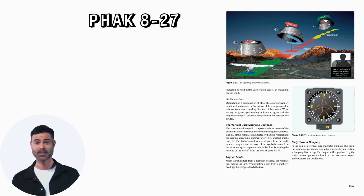Oscillation error. Oscillation is a combination of all of the errors previously mentioned and results in fluctuation of the compass card in relation to the actual heading direction of the aircraft. When setting the gyroscopic heading indicator to agree with the magnetic compass, use the average indication between the swings.